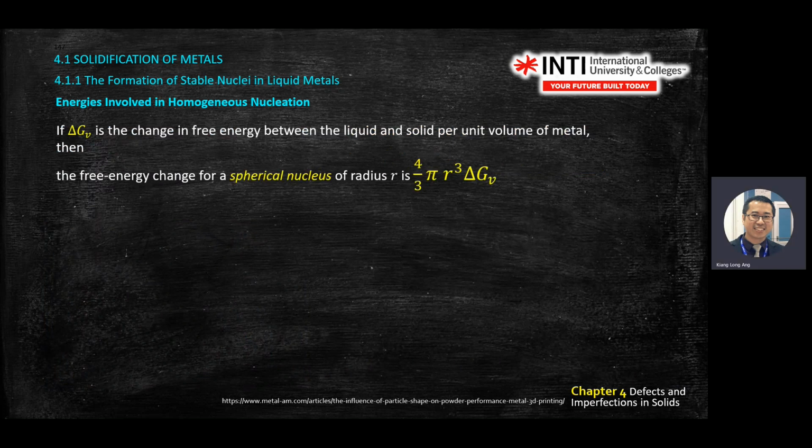So we start to develop the equation for energy. Again, the symbol we use for energy for nucleation, meaning starting to grow into bigger size, is delta G. We start with a spherical nucleus because we are assuming we are looking at pure metals, and the metal that forms starts as a complete sphere. For a complete sphere of radius r, the energy change will be the volume of the sphere, 4/3 pi r cubed, times the energy.